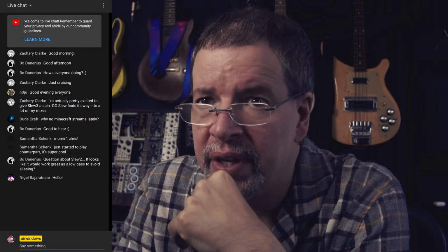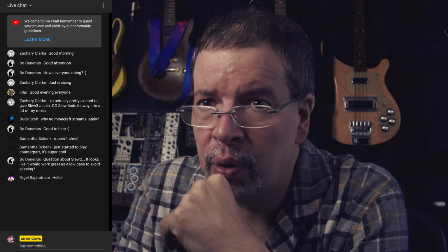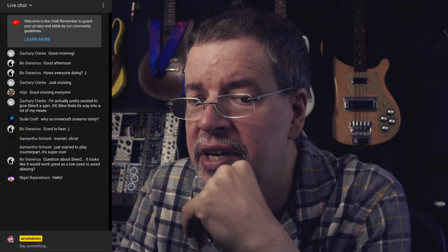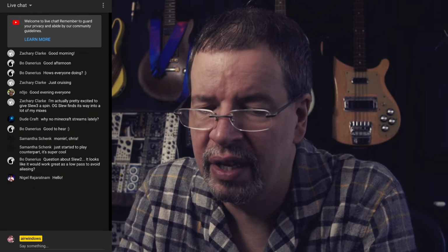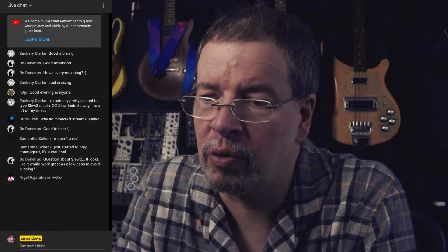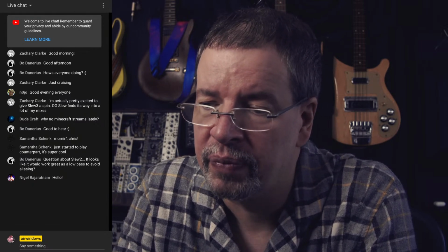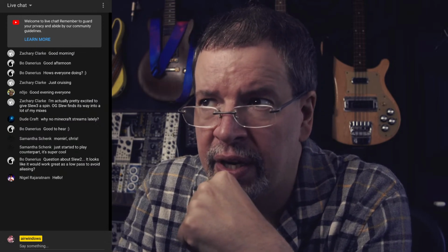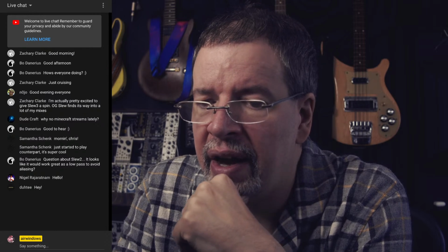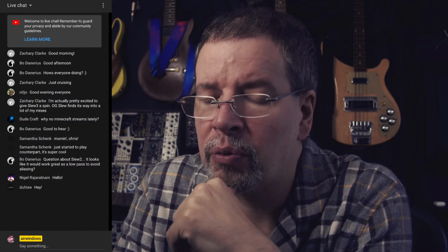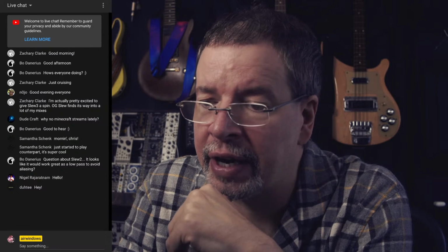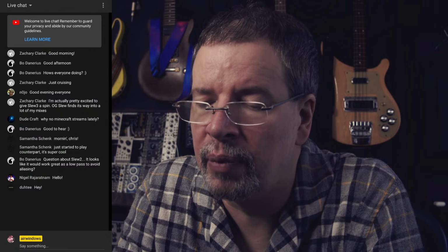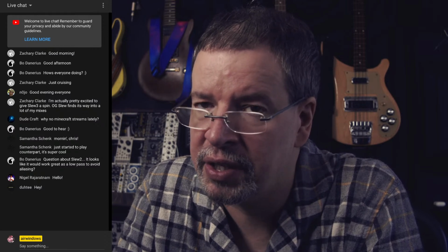Now, Bo is asking about Slew 2 as a low pass to avoid aliasing. Well, the thing is that it doesn't roll off quite. If you really wanted to obliterate aliasing, what you would be doing is, I think, depending upon what kind of distortion you're producing, you'd have a brick wall filter going down to about half the Nyquist frequency. So if you could brick wall filter everything above 11K at CD quality rate,